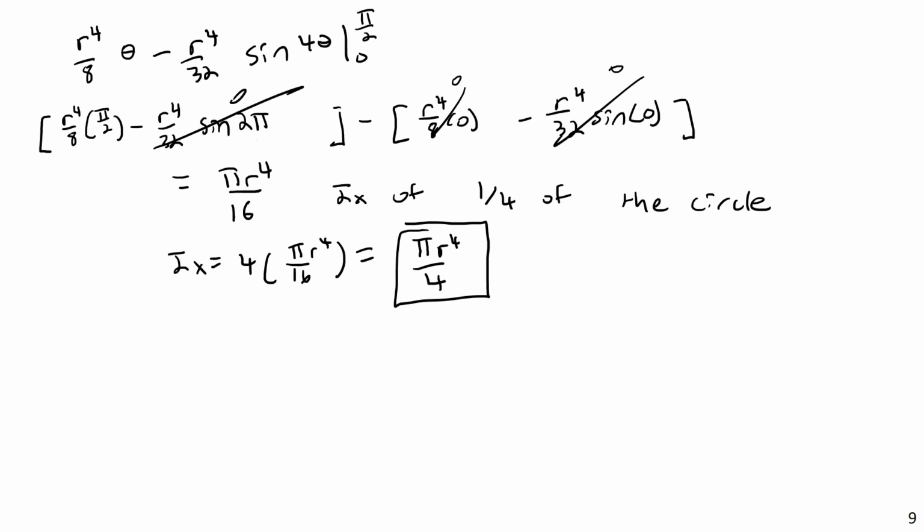Now, unfortunately, we're not done yet, but actually we are almost done, because the final step, the only one that actually involves the parallel axis theorem, is rather simple for this particular problem. The second example will involve a bit more work. But here, again, we have our circle, and we have calculated the moment of inertia about x. When I said the original problem said calculate about the x-axis, in the context of moments of inertia, this is basically my Ix prime, and we have this distance h here.